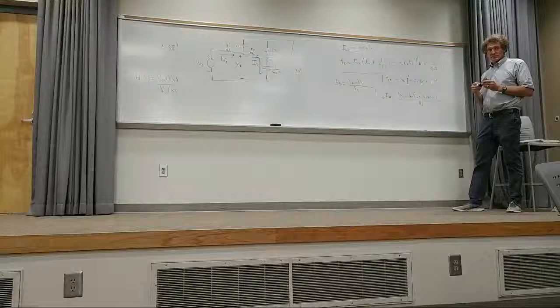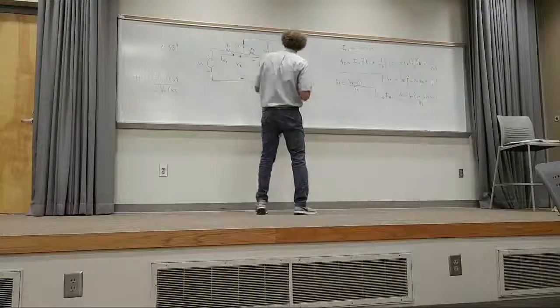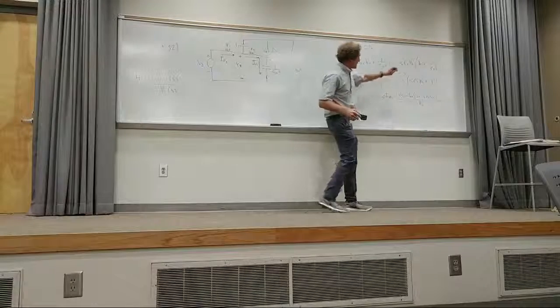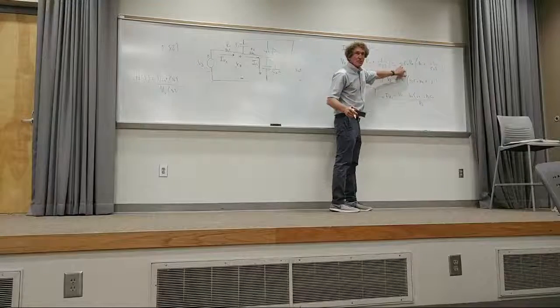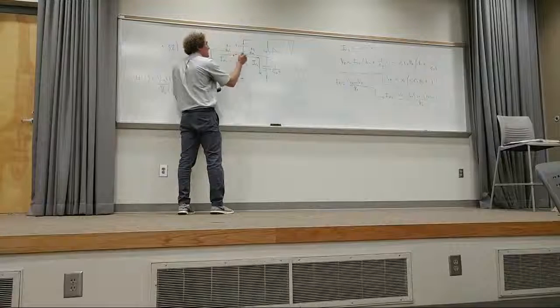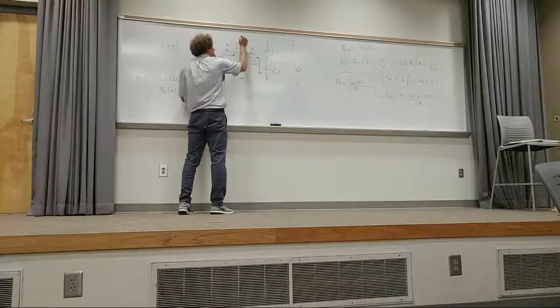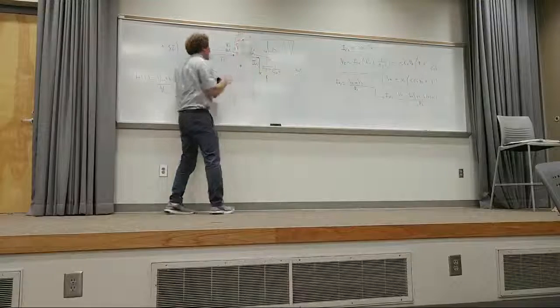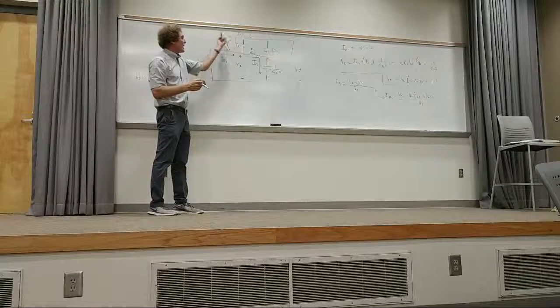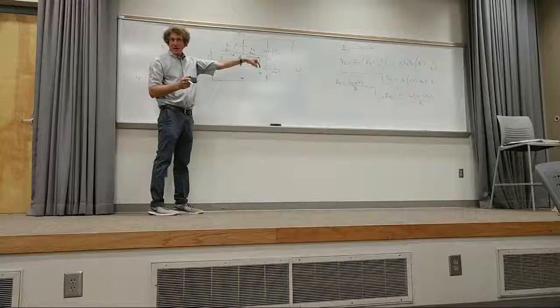Agreed? Right? Now that's IR1 flowing here. This is IC2 right here. You'll notice they both are in terms of V naught and Vs, right? What do you know about that? That this current has to equal, depends which way you want to take it. If I take the current going this way, call that IC1, I know that IR1 has to be equal to IC1 plus IC2, correct? Agreed? Y'all see what I'm doing?